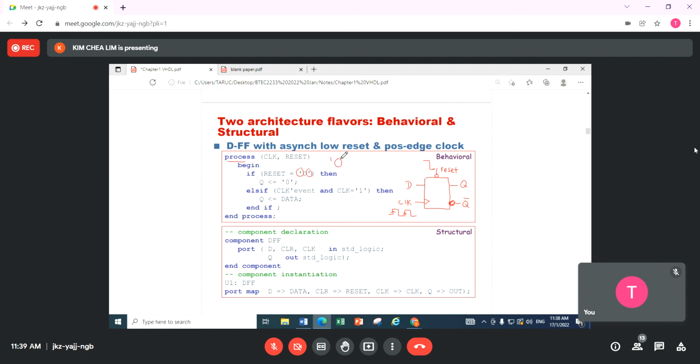If you want to talk about logic, you always have the open inverted comma, close inverted comma, indicating that this is a logic, not the number 0. It is a logic 0. If reset is a logic 0, then my output is also a logic 0, reset to 0. So for this output here, we use this type of assignment. Output is assigned to logic 0, or 0 is assigned to output. So this is an assignment.